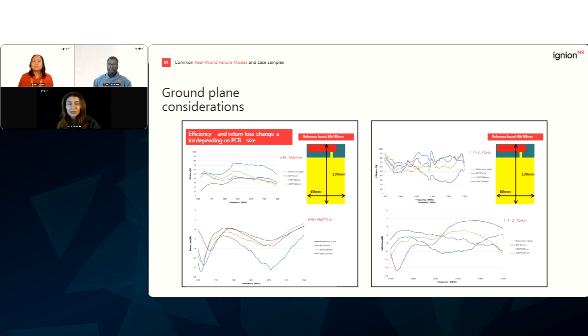We can see here like 70, 60% in different frequency bands. But in the datasheet they always say that we tested it on this reference board with this size. For example, here, 130 millimeters by 60 millimeters in width. And this antenna will only show this efficiency in these S parameters only on this reference board.